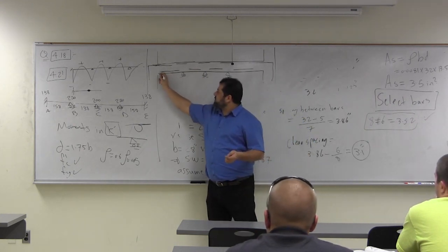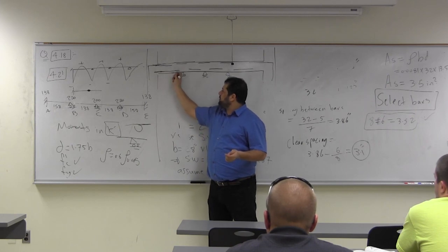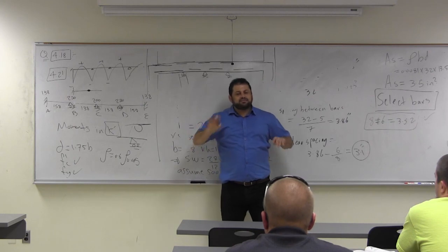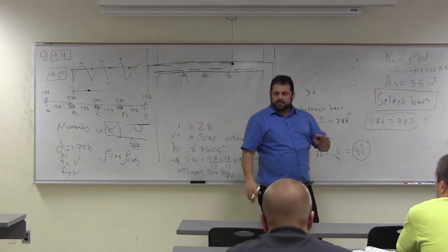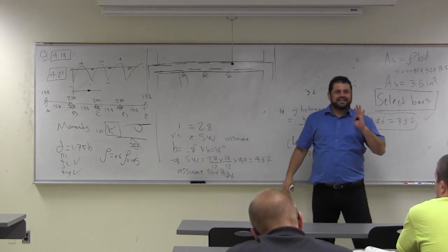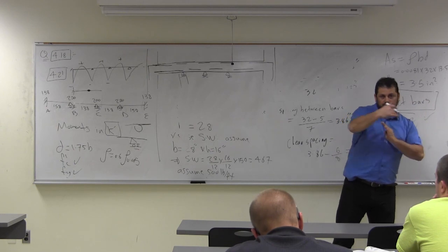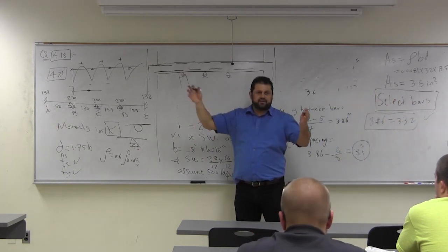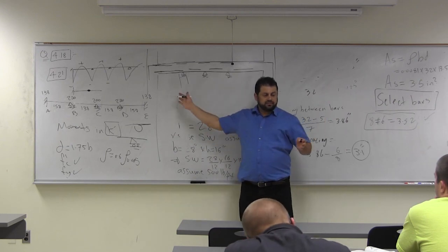Okay, here, how much do you get this into this support or into this support? Because remember, this is a column. At least 15 centimeter, which is 6 inch. At least must go into the column 6 inch. This is steel. There are requirements given. There are sketches given for you.